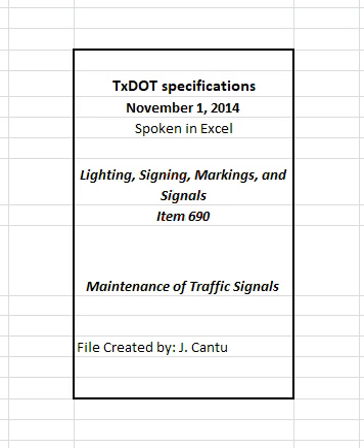4.21 Preservation of sod, shrubbery, and trees. Preserve all sod, shrubbery, and trees at the site during the contract. Obtain permission to remove any sod, shrubbery, or tree branches. Preserve and restore sod and shrubbery into their original position. Replace damaged sod or shrubbery at the contractor's expense.